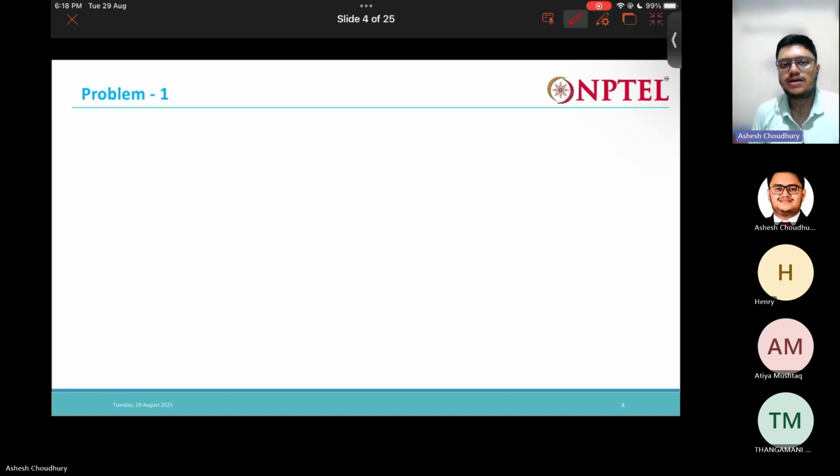The vertical pressure times the earth pressure coefficient will give us the horizontal pressure. In terms of Z, that is the height, we will write that expression down first.